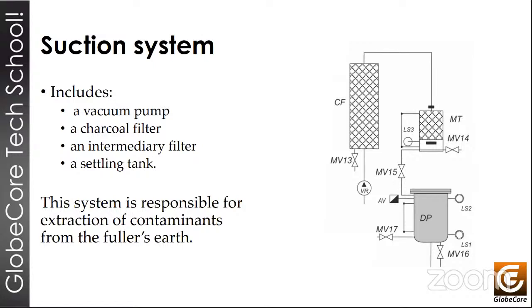And the second function is that after completion of the burning, the reactivation, the system increases the amount of passing air. And since there is no more burning, basically what it does is cools down the sorbent, which is necessary when we need to start processing oil and regenerating oil again after sorbent reactivation.